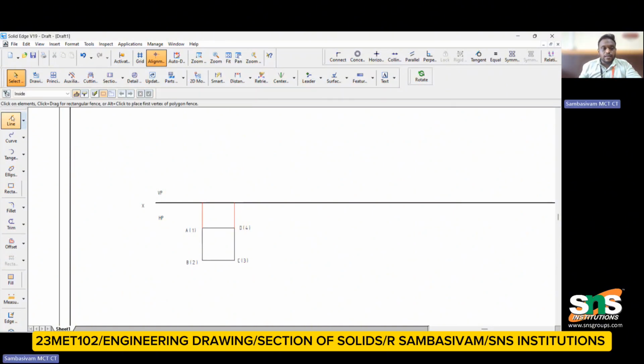As I said earlier, this is a midpoint. We can draw the midpoint from this axis. The prism is normally surrounded by rectangular surfaces, so it will be mentioned as 50 height. I have drawn this axis line. Similarly, from this point I have to draw a line of 50 height, then place it here, then draw another line from this height of 50, fix it here and join it. This makes the surface equal.